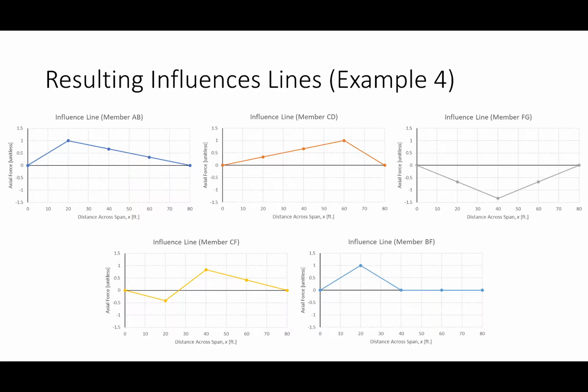What I'm saying is, first off, I do want you to recognize the pattern. I will also be candid about something. There is a practice problem. I had a problem when I took the FE exam, a truss influence line problem: here's the truss, what does the influence line for member CF look like? And I looked at it and said, C, move on. Because it was an inner diagonal member, and I knew that internal diagonals flipped.